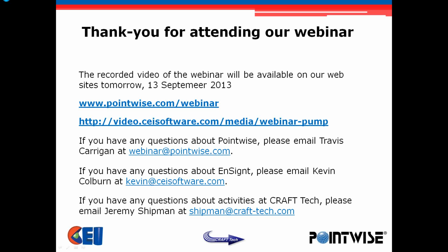The intermodule boundary condition can handle non-contiguous interfaces, but certainly the accuracy of that interface is better if you have the cell faces on one side of the interface similar in size to the other. So certainly point-to-point match is the best, but in cases where you cannot do that, the interface boundary condition can handle a non-point-to-point matching.